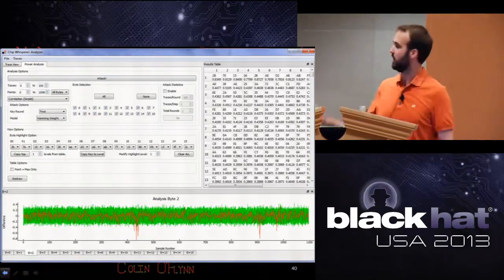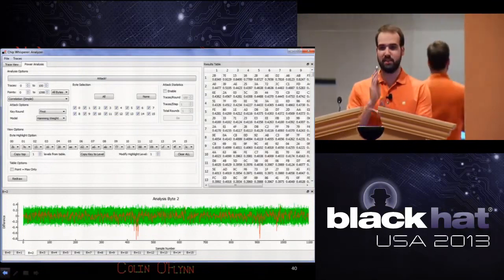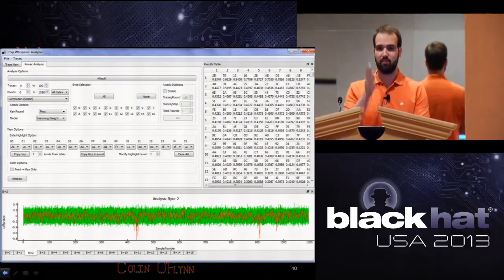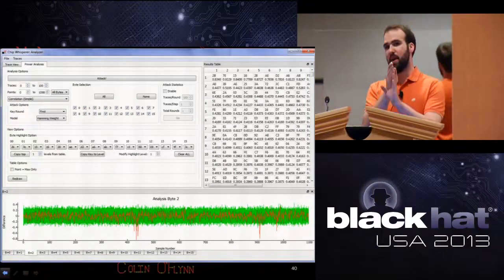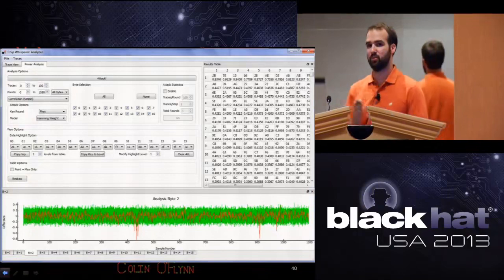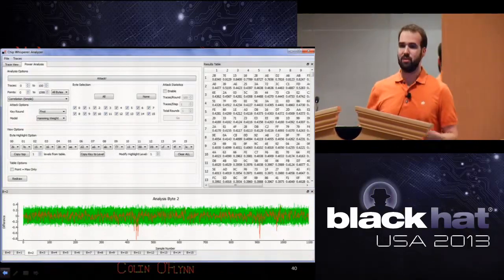On my system, I start the recording for the testing right when the device puts a clock line high that says I am now doing encryption. So it's perfectly synchronized. I know from that point there are X cycles before the encryption. So they all line up. They do have to line up. If they don't, it won't work.